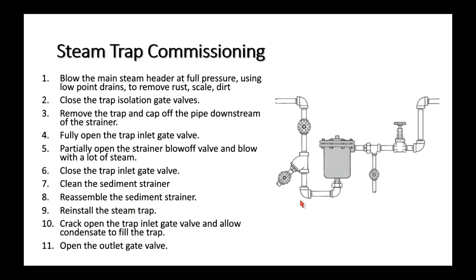So for steam trap commissioning, the text has got this big procedure. So let's say this is a new trap here. So here's the big procedure. You can kind of reason this out yourself. Before I install the trap, I'm going to have the inlet valve shut, and I'm going to have the discharge valve shut. And I'm going to put a pipe cap on the end right there. So I haven't completed the installation.